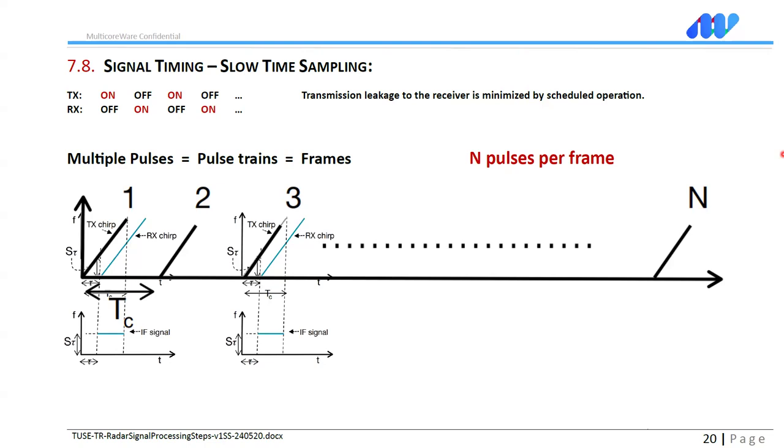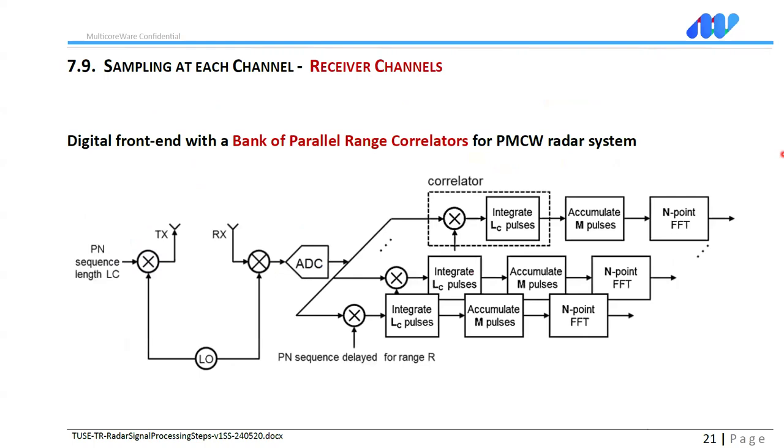So here we are going to see there are two dimensions for the receivers to collect data. One axis is for the first chirp, and we call it the fast time. And once you start collecting the second pulse, third pulse, fifth, and it goes on forever maybe, you call it the slow time. We're going to come back to this.